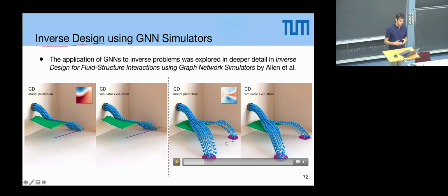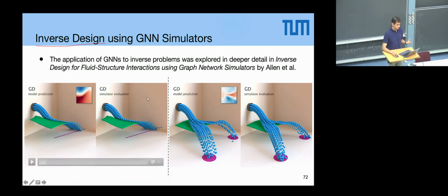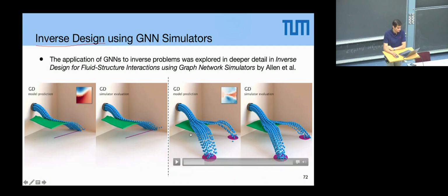So if we consider how these simulations are done, this is done as before. We have some nodes for the fluid, we have other nodes for this green surface. Also, we haven't seen how to work with inlet boundaries, but here we are just creating nodes. So we fix some flow rate, and we are creating nodes at that specified flow rate. That's how we simulate the inlet. And this GNN is able to simulate these balls going down due to gravity and colliding with this surface, because we can work with different kinds of materials and we can time step.